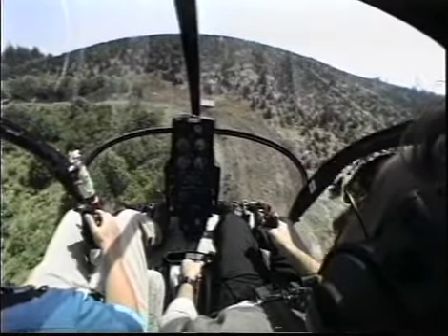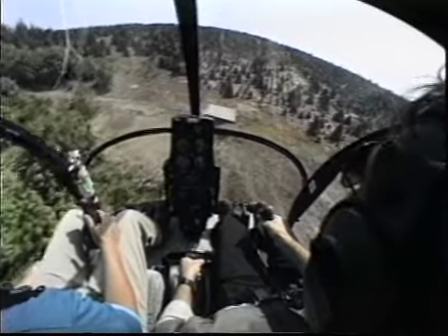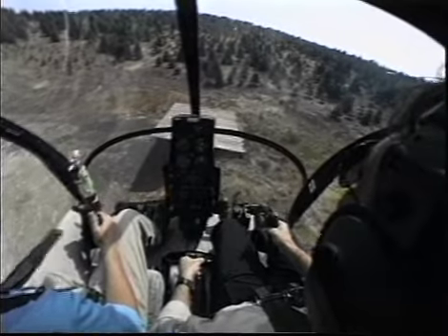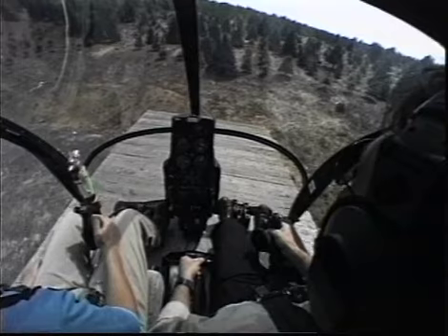These same considerations apply to pinnacles and ridgelines also. A pinnacle is any area that drops away on one or more sides. Typically, we think of mountaintops and ridges, oil platforms, and rooftop heliports. But even landing on a sidewalk with a curb qualifies as a pinnacle operation. Remember this rule of thumb: if the helicopter can fall off it, it's a pinnacle.